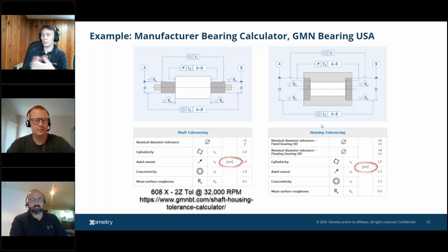That being said, if I'm a university robotics team, I may be okay with running a reamer through at that 22 millimeter diameter, because that's still like 5/10. It's still extremely tight tolerances, and then press fitting that in and having, I would say, a 98% confidence of the function of the part. So there's what the manufacturer says. And again, if you're working in major critical applications, absolutely tolerance this, talk to us, we'll get the quote out. But if not, you could save a lot of cost by saying, all right, doing a ream is okay.